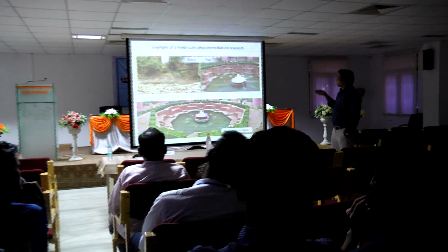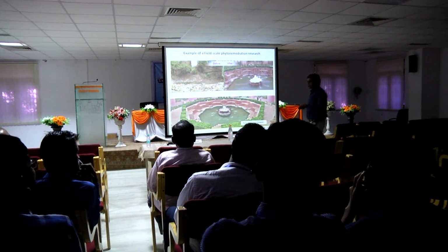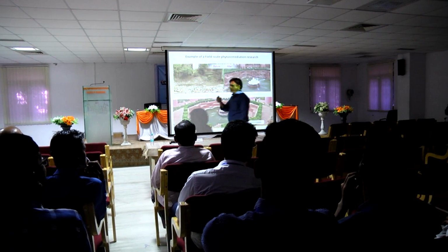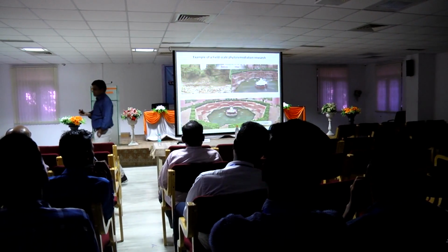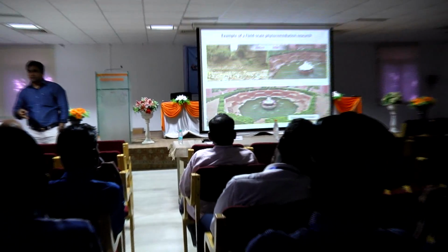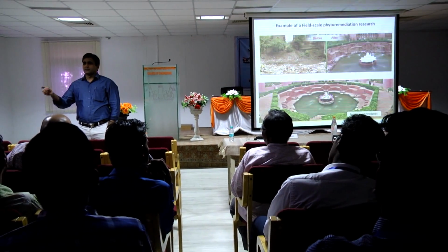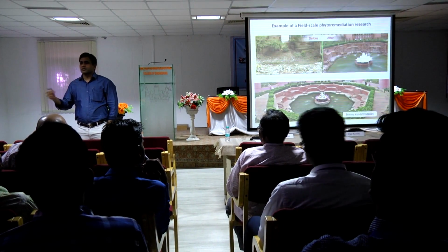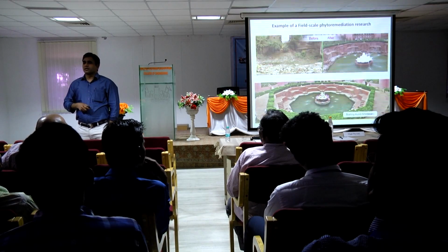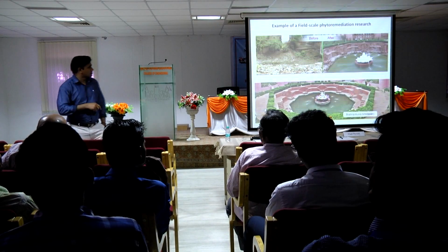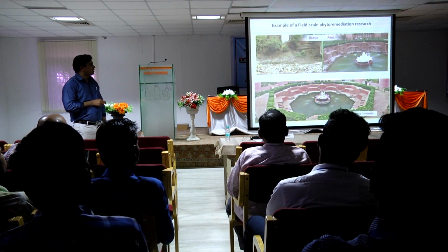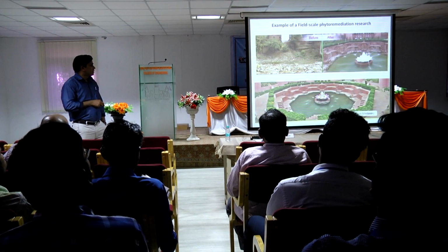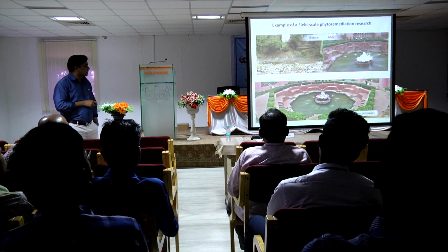And what we observed was that after a week or so, the water was very smelly. The water which was filled in this cone was very fresh initially, but after a week or 10 days, a foul odor was coming from this water. The water quality was deteriorating within a week. So to improve the water quality of this pond, what we proposed was to make a treatment wetland around this pond.